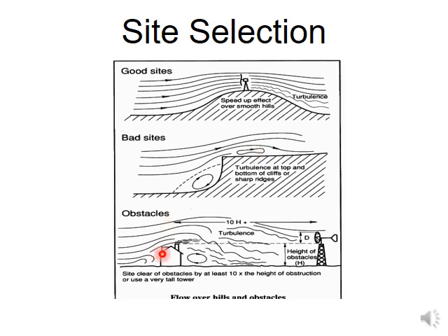And here we know that in the area of the flow of the wind there should not be any obstacles, because obstacles also affect the wind velocity and create turbulence in the wind, which will ultimately create non-uniform velocity at the site of the windmill.